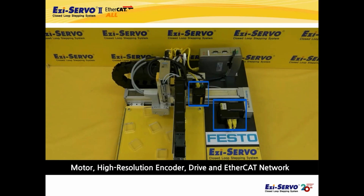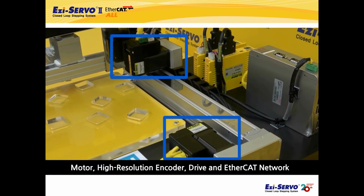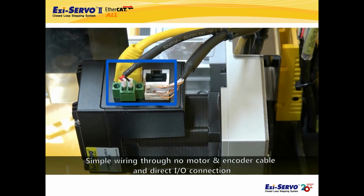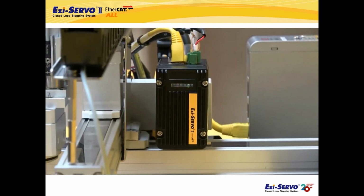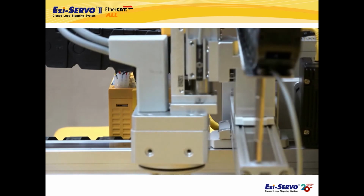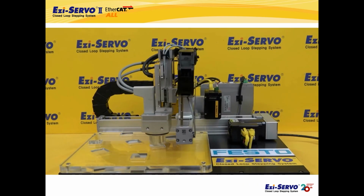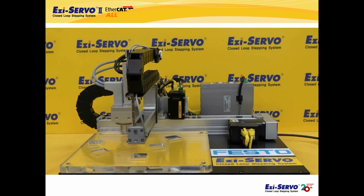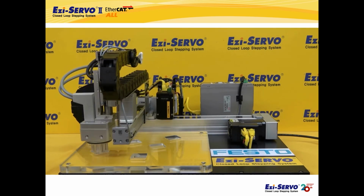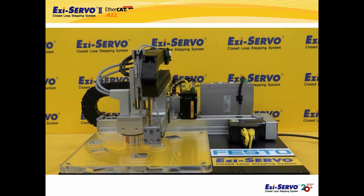Ezi-SERVO II EtherCAT ALL is applied to 2 of the 4 axes. Since it is an all-in-one type product that combines a motor, a high-resolution encoder, a drive, and EtherCAT network, there is no need for a motor cable or an encoder cable, and it only needs a power cable and a network cable, which saves the wiring. Also, it does not require a separate space for the drive, making it ideal for these small Cartesian robots.